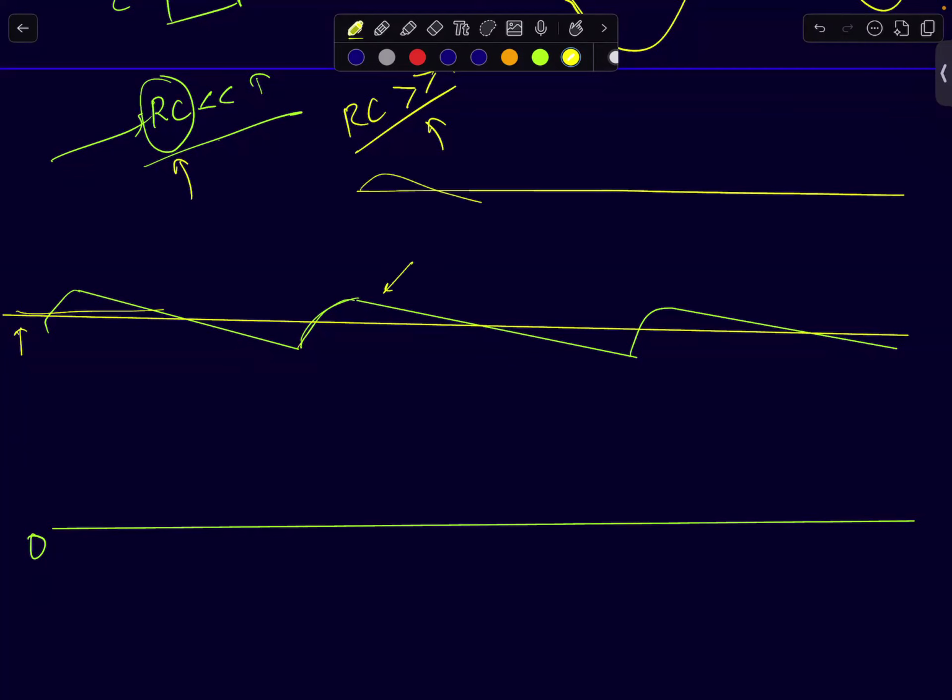And the rate of this variation will be equal to the input frequency. So normally, if you're deriving your DC signal out of a 50 hertz or a 60 hertz source, the ripple's frequency will be that 50 or 60 hertz. Now if you see, the capacitor has a finite DC voltage. The average value of the capacitor voltage is finite.